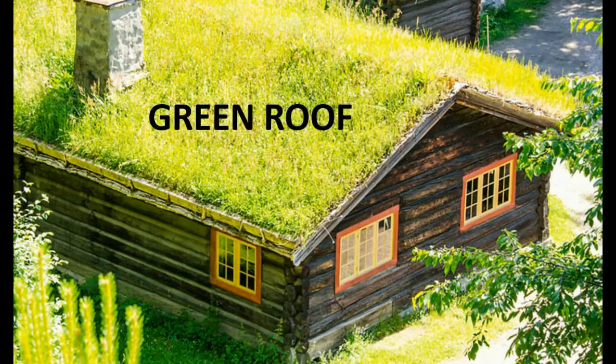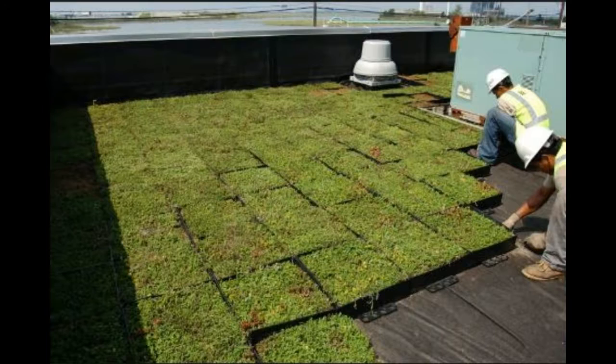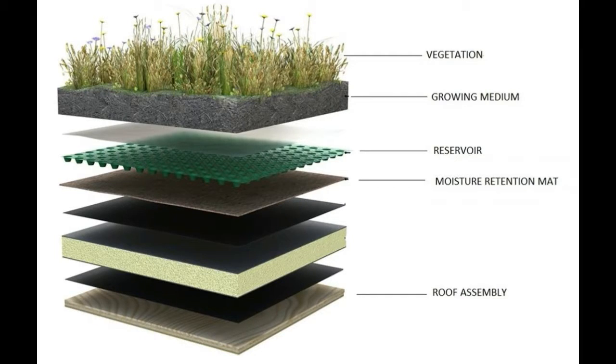Green roof is another way to approach net positive energy for various buildings. It describes the general concept of a vegetated surface layer covering a conventional roof. The typical green roof system includes vegetation, filter layer, growing medium, drainage layer, root barrier, protection fabric, insulation, roof deck, and waterproofing membrane.